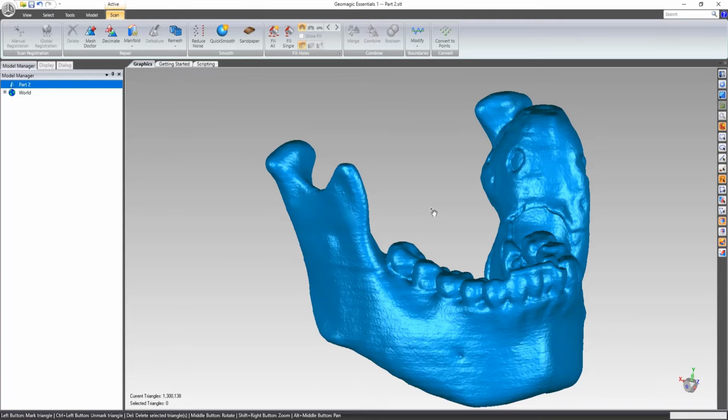Autosurfacing is the Geomagic process to create a NURBS surface model. Autosurfacing consists of 3 different layers of spline networks. The first layer is called the contour curve network. The second layer is called the patch curve network. The third layer is called the grid network. All of these spline networks are connected to each other to create surface patches, which are fit all around the part.